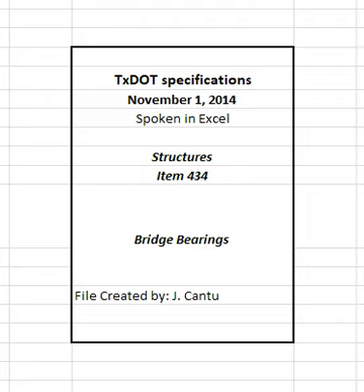Plain bearings may be molded individually, cut from previously molded strips or slabs molded to the full thickness of the finished bearings, or extruded and cut to length. The finish of cut surfaces must be ANSI 250 or smoother. The finished bearings must have no voids or separations detectable either at the bearing surfaces or within the bearing.